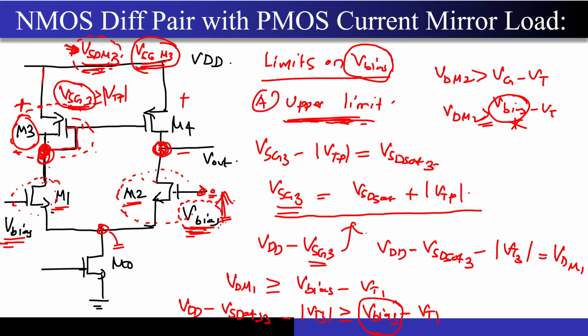Because these node voltages that you are seeing over here should remain fixed. If they start changing, then there will be a contradiction, which sir has already explained. We usually expect I0 by 2 and I0 by 2 current to flow over there. Now if these two voltages become different, the pair will not work in a symmetric manner. Some extra current will flow over here, and that extra current will get dumped into this transistor as well because of the current mirroring action.